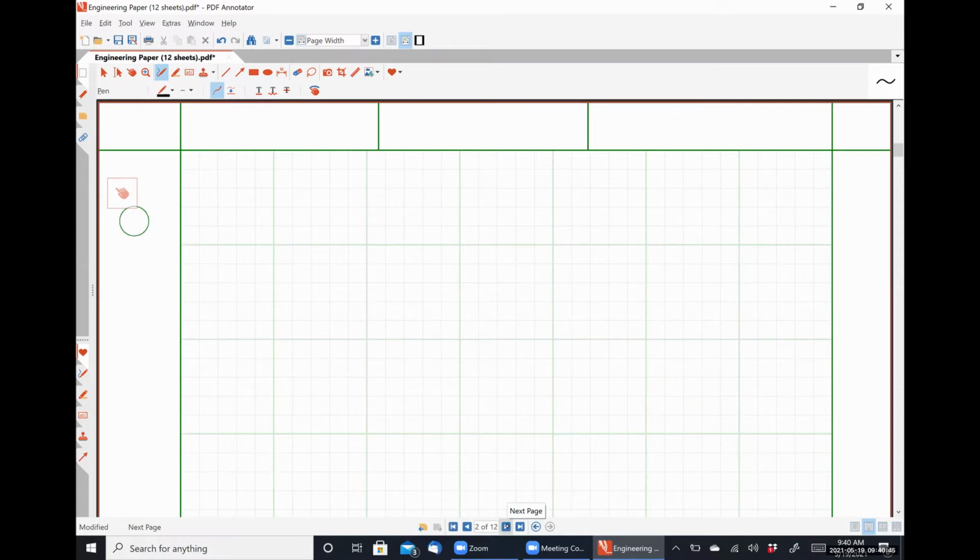So under the constraint that we're using a practical system, we're going to have something that looks similar. We have our signal source I sub S, but now we're going to have some signal resistance or impedance to take care of as well, which I will call R sub S. So if we look in here, we see our input resistance with feedback. If we look in here, we just see the input resistance of the system where the signal impedance has been taken out.